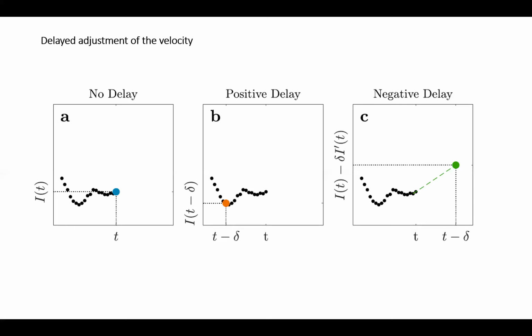And there is another type that is called a negative delay in the feedback, which means that I have the structure here, and I estimate from the latest values I measured of the light intensity. This, of course, can be done with more complicated approximations or extrapolations. You can take, for example, the last 3, last 4, last 5 data points, depending on the frequency of your measurements. And you can make quadratic or higher order fits to this, or any kind of different fits. But the simplest way, that we are sticking to, is a very simple linear extrapolation using the last 2 data points. And we extrapolate the value of the measured intensity to a time in the future.